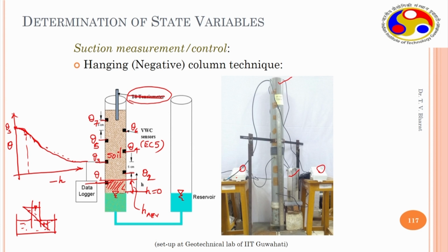Similarly, now if I raise this water level to a certain depth, now this sensor realizes that the water content at this particular depth and at this particular depth both are theta s only. Now, this theta 3 would change and theta 4 would change. Now, you need to estimate what the head is from this particular point onwards. You get new points in between again.